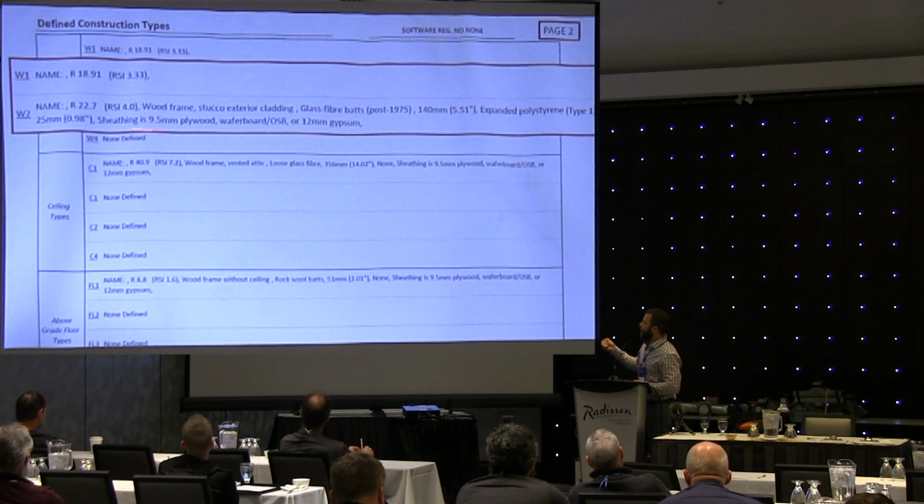So I'll just let you know, too, in our software, we let people just input the R value directly. Like I said, I'm working for a builder. The builder needs code minimum. I know code minimum is 15.78 R in the wall effective, so I'll just type in 15.78. I'm done. That's all I need to do.